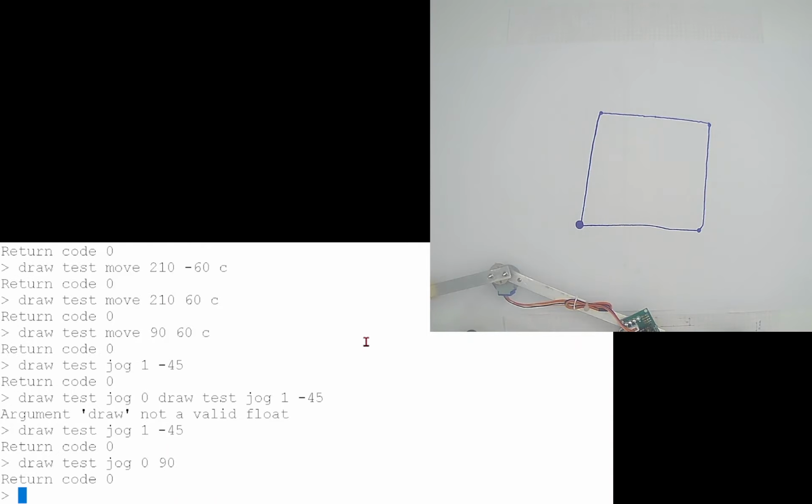So there you have it. It's not as bad as I thought. It looks pretty much like a square. It's obviously skewed. And again, that's because based on which direction the forces were pressing on those stepper motors, it would move one way or the other due to the backlash. So I'll take that.